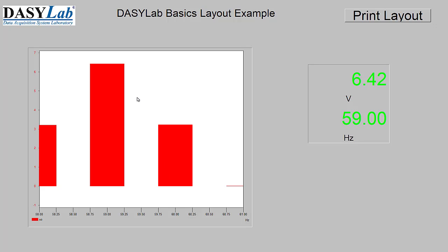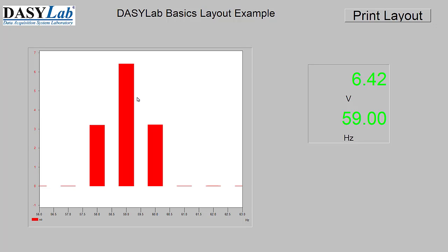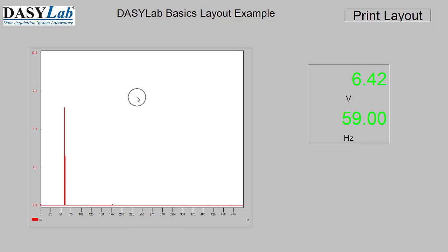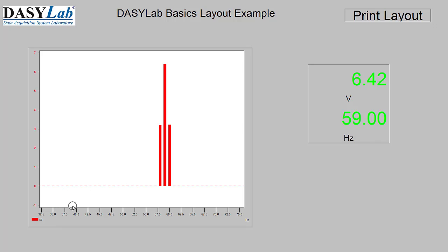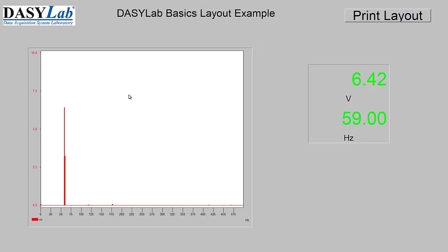And to unzoom, you're going to control right-click once. That takes you back to the last step, and then right-click a second time, zooms all the way out. So this works the same way the zoom does in the worksheet view, except it's all keyboard and mouse control, and not clicking on a zoom cursor on the top of the display window. So control, now click and drag. So I'm using the left mouse button to click and drag, and then control right click to unzoom.